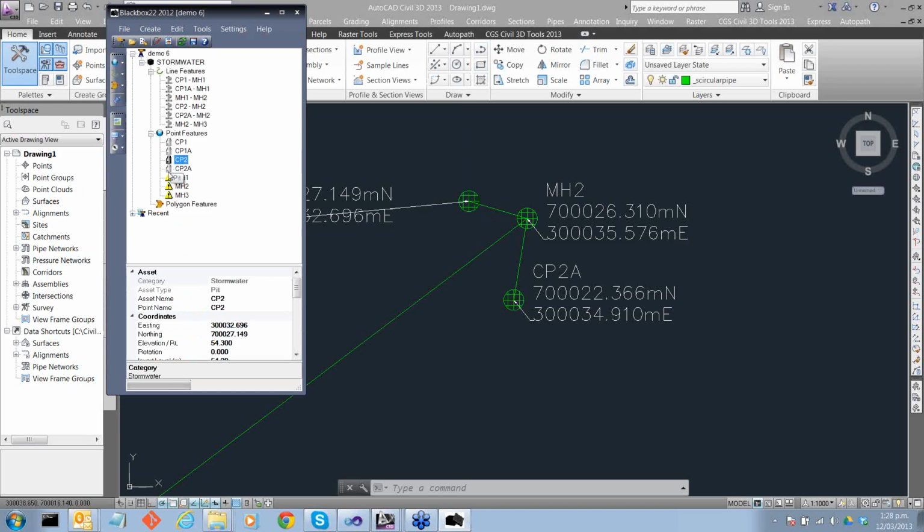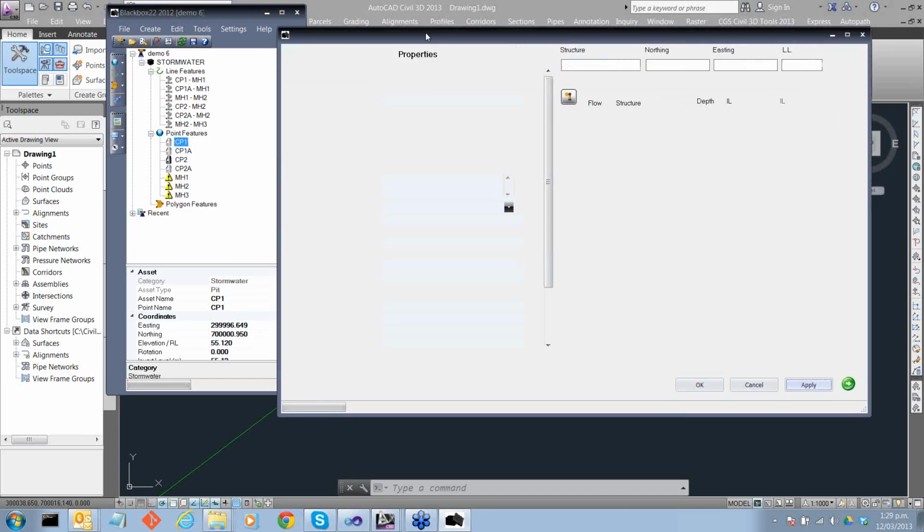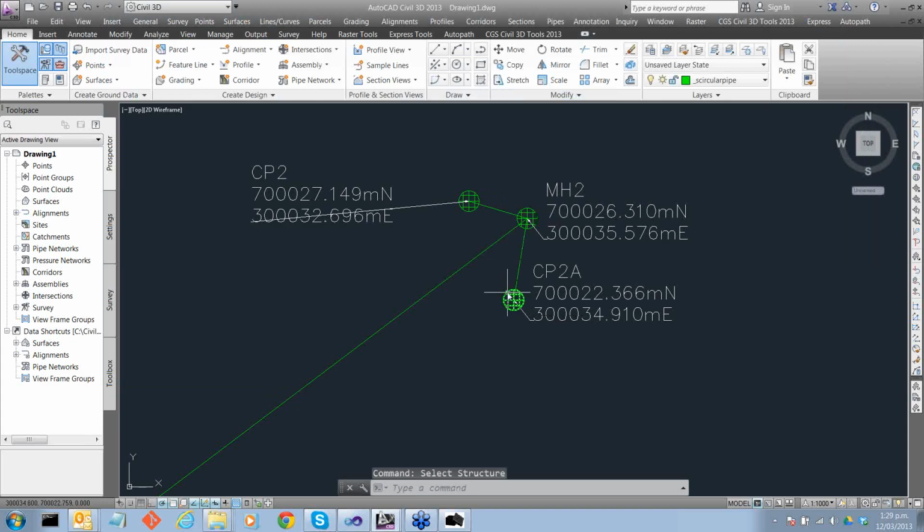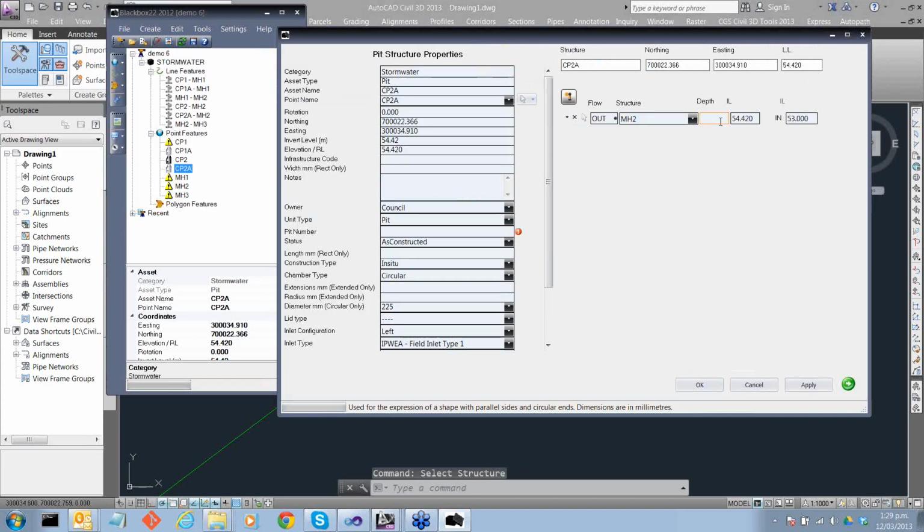The other ones are still gray. That's just a signal to let me know that, you know, if I've been giving this demo and haven't really been paying attention, or I've gotten up to get a cup of coffee and come back, and I've forgotten exactly where I left off, this lets you know exactly where you can start back up again. So I just double click that to open it up, or right click, and give it a depth, and click OK. And so again, I can select it this way if I want to.